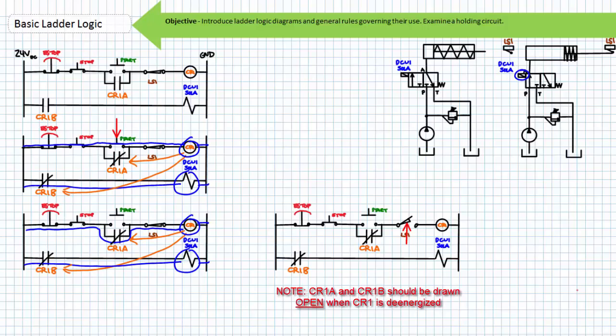Our progressively more complex ladder logic examples illustrated this fact. Every time a new device or connection was made, this necessitated a technician physically rewiring the inputs and outputs to yield the newly desired functionality. In contrast, to change the functionality of an electrically controlled system employing a PLC, one must simply reprogram the system. This is to suggest that an electrically controlled system employing a PLC is significantly easier to install, modify, and troubleshoot than those employing traditional hardwired relay-based ladder logic.